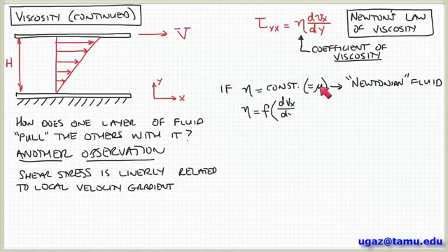Now, for many other kinds of fluids, the viscosity coefficient may not necessarily be constant, and it's often the case that this coefficient depends on the rate of deformation, or this velocity gradient. And if that's the case, then the fluid is said to be non-Newtonian. One example is a lot of polymer solutions, or polymer melts, surfactants. A lot of things like that are examples of non-Newtonian fluids, and a lot of times they exhibit what's called shear thinning behavior.